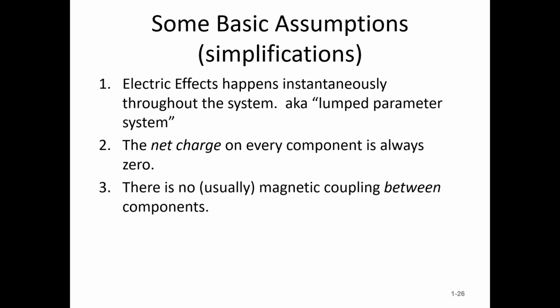Okay, also the magnetic coupling or the magnetism that's in an inductor, or actually in other devices, but much smaller magnetic coupling, but an inductor has a lot of magnetic field around it. If you put two inductors together in close proximity, like right next to each other, the magnetisms are going to intertwine. We call that magnetic coupling. So the magnetism in one inductor is going to affect the other inductor. Okay, that messes the circuit up, and we're going to deal with that a little bit.